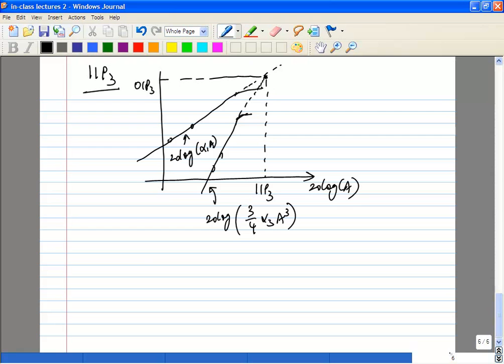Okay, so it's quite easy to calculate, right? Let's say the power is AIP3. Obviously, since the two things are equal, the gain here is alpha 1 times AIP3, because you're going to extrapolate and make them equal. So what you'll see is your IIP3 is going to be a function of alpha 1 and alpha 3, your first and third order cubic nonlinearity. Alpha 3 is a cubic nonlinearity. Alpha 1 is your fundamental gain.